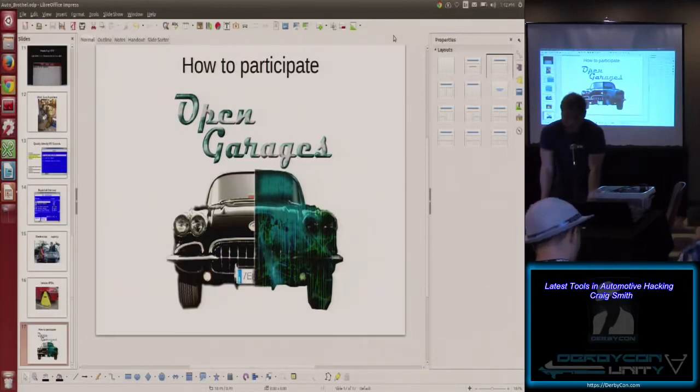What I would recommend though for breaking those, there's a couple ways to do it. But from a tool perspective, Caring Caribou has Nmap-like things, but it also can be used as a framework. I have a module I haven't released, but you can make one too, that does the same kind of thing. For one of the vehicles, it requests the seed, and then I just start brute forcing the key. And what will happen is it'll eventually lock you out. After like 3 tries, you get an error code saying too many tries.